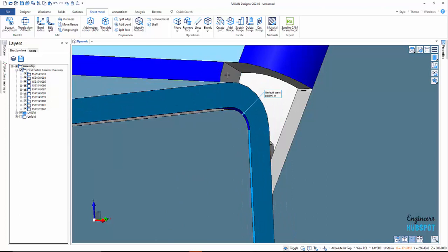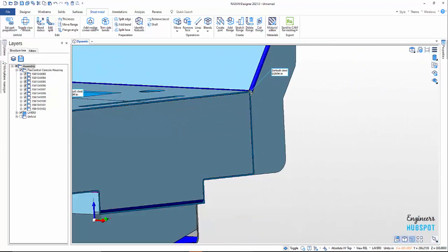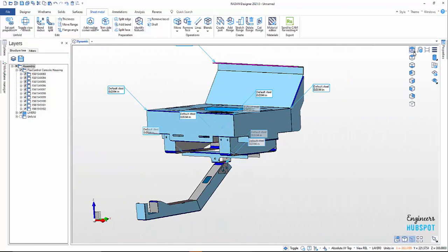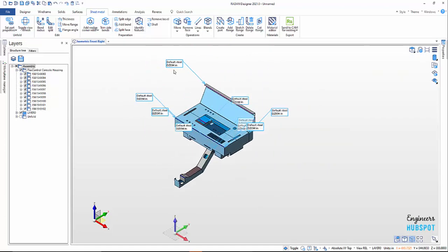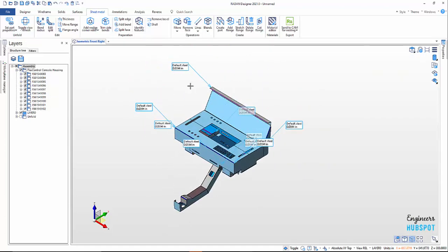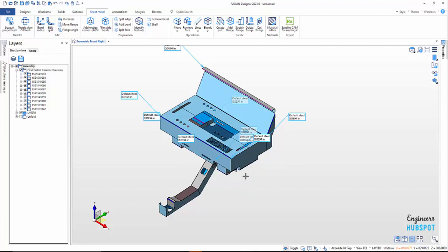This face here was preventing it from unfolding, and this was a step file. I've noticed quite a few people have issues with step files and unfolding using Inventor. So that's what I've found. But once you figure out what's preventing that, you can easily fix it.